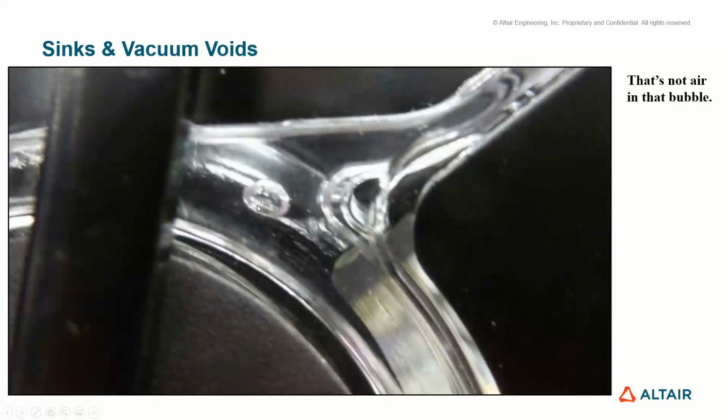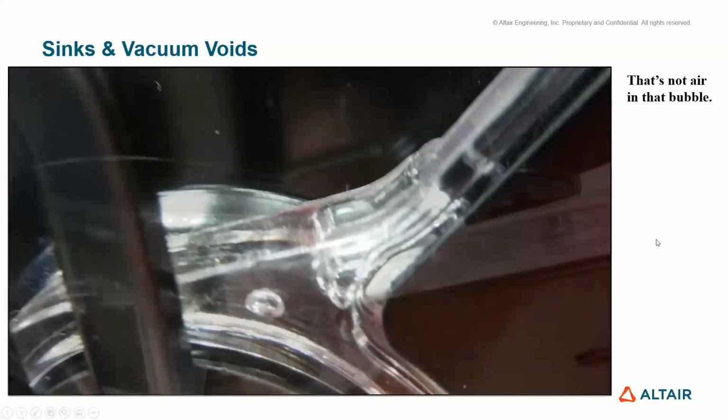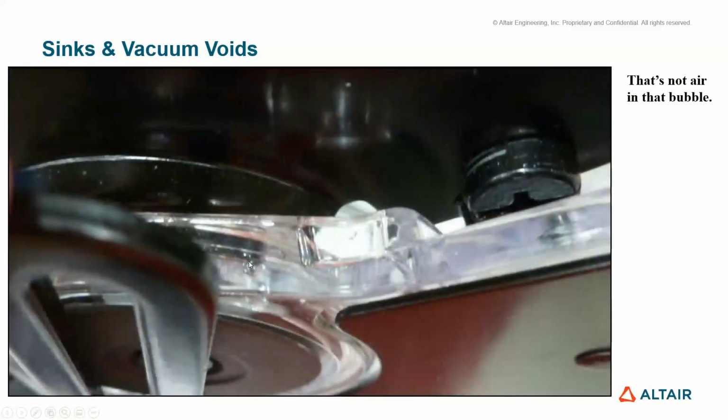Here's a much cleaner image of it. There's that little vacuum void in there. And so this is shrinking away from the geometric center or the thermal center of that geometry. That's why you're seeing that there. That's the thermal center. Another angle of the same piece, right? There it is right there, right? Vacuum voids. And one more. It's actually pretty clear there. This is a little distracting, but there, nice and clear.